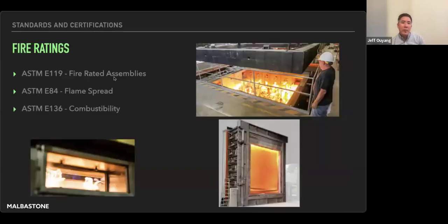This next section I really put in here just because it's really cool to have photos of fire. But this is really one of the best properties of magnesium oxide. Magnesium oxide's other use is actually as a refractory material. So you'll see it a lot lining the furnaces of steel plants, and even the crucibles used for pouring steel that you see in Terminator. A lot of those are magnesium oxide as well.